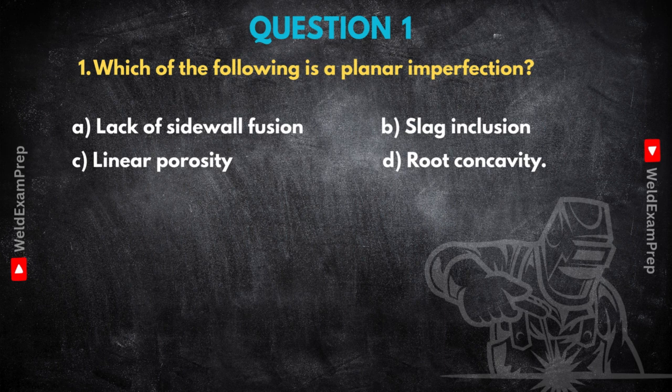Okay, take a moment. Try and visualize those options. What does planar really mean in this context? Right, that term planar is absolutely critical here. It's key because it describes the two-dimensional nature of the defect, often flat, sort of sheet-like. Like a plane, basically. Exactly. Unlike, say, a volumetric flaw, which might be more rounded or irregular in shape, a planar defect is like a thin crack or maybe an unbonded interface.